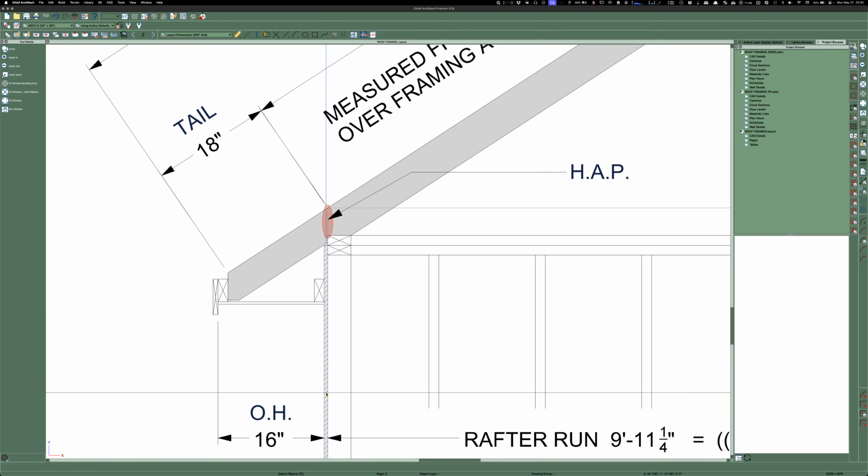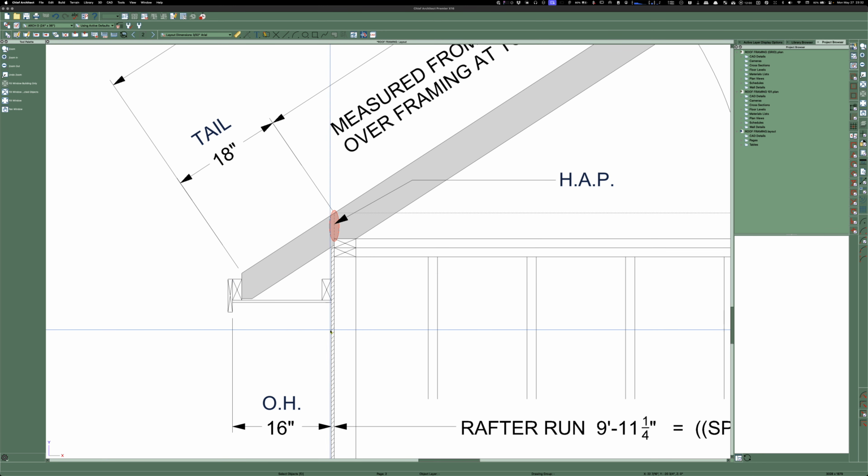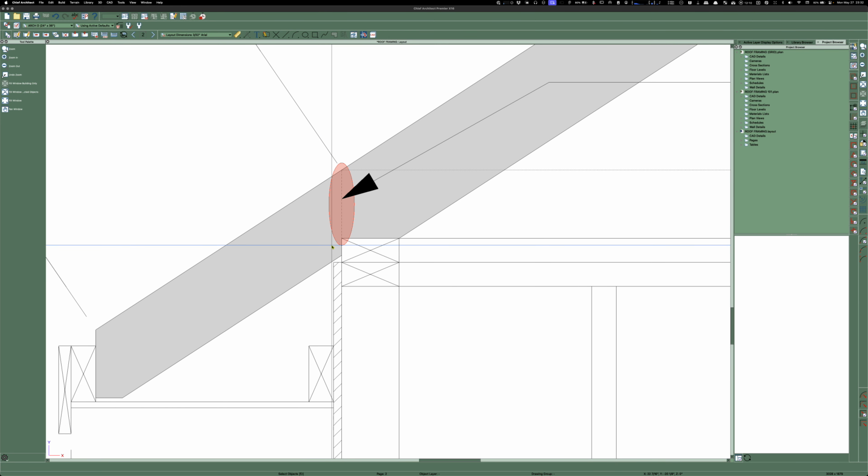And in my entire framing career, when I started, we would put the rafters on framing with no sheathing because we were building on slabs, and we would level everything and brace it out. And then we would sheet it after the fact, and we would just tuck the sheeting up as high as we could get it. It would hit the rafter tail, and then we would nail it on. And I was looking at this going, because like Washington State with all the trusses, the truss stops here and goes up like a 1/4 inch, and then the 2x4 comes down. So plywood can work all the way to the top.